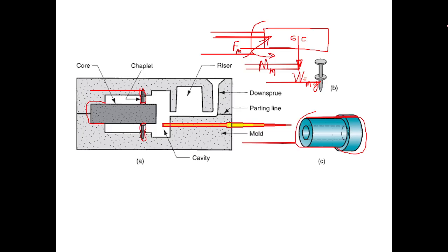So the surrounding fluid particles apply a certain force system, and the resultant of such a force system is called buoyancy force. And the line of action of the buoyancy force passes through the centroid of the volume. This is in drawing the free body diagram. Yes, don't forget to show the buoyancy force.